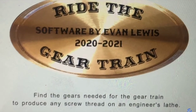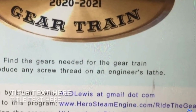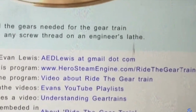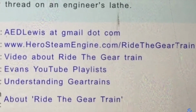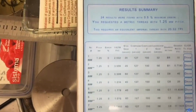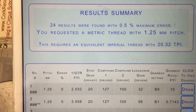One way to find out how to set up your lathe to cut a particular thread, particularly if it's an unusual thread, is to use my computer program, which I make available free of charge online, called RideTheGearTrain.com. So give that a try. One of the advantages is that you can enter your own set of gears, and it'll tell you which ones of those gears may be used to set up the gear train and gearbox to give the thread you want.